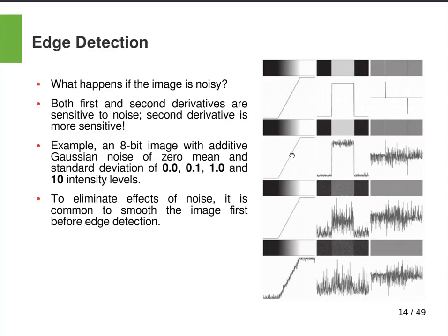Of course, since the level of noise is not very large, it is very hard to see it here. But on the other hand, in first and second order derivative results, we have more sensitivity to noise, because since we are calculating the difference between neighbor pixels, this magnifies the amount of noise.